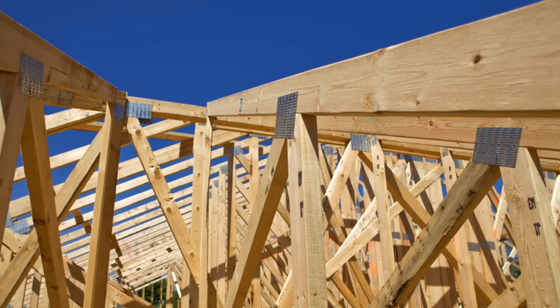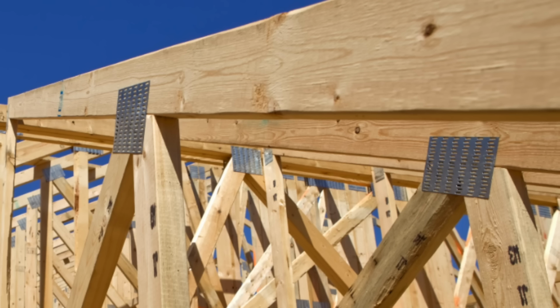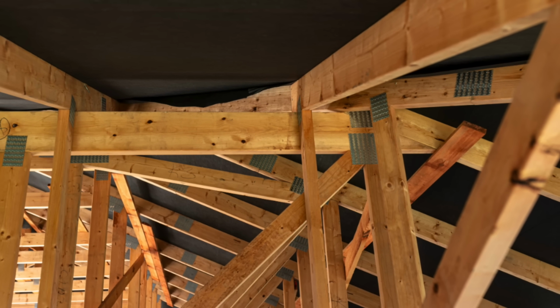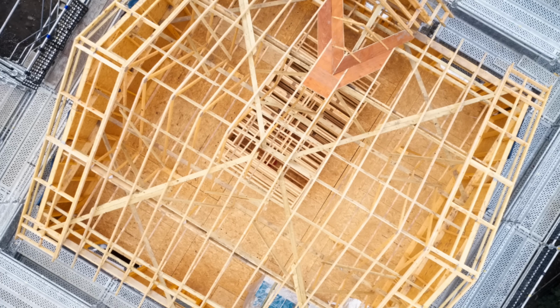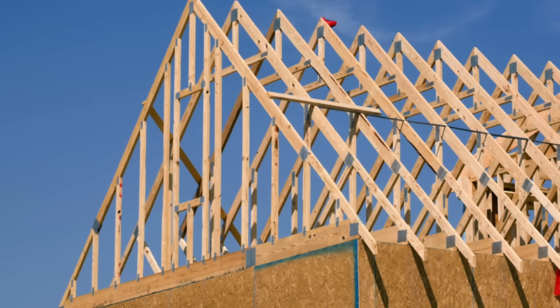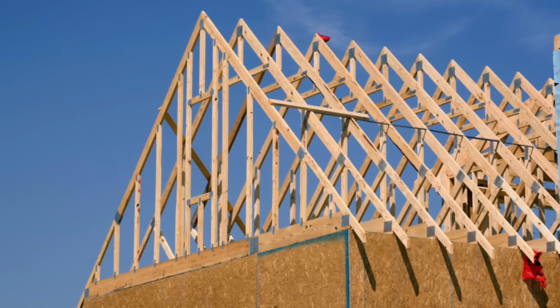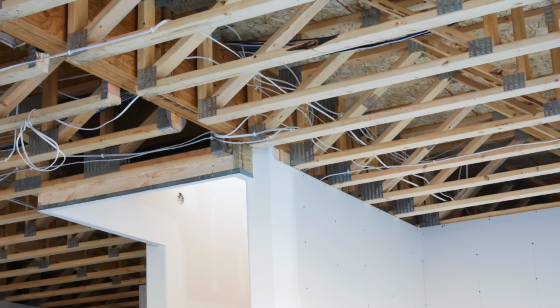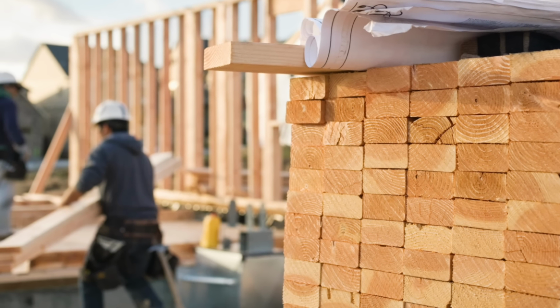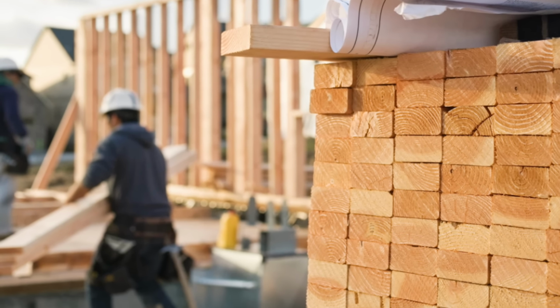They're made of much skinnier, shorter pieces of lumber, pinned together with spiky metal plates. Altogether, they create sort of a web, and that web is very strong. In fact, it's so strong that most truss roofs don't even need load-bearing walls beneath them. They act like a big girder spanning from one outer wall to another. Trusses are also sometimes used for floor systems. They're very strong, they speed up construction, and they cut down on the amount of large dimensional lumber that we used to need to build houses. So you've got traditional roofs with rafters, or you've got trusses. Kind of two different worlds.